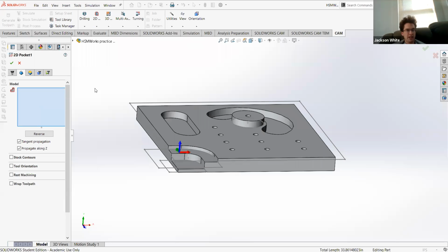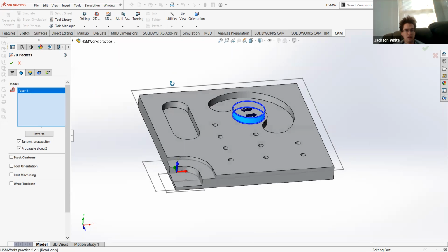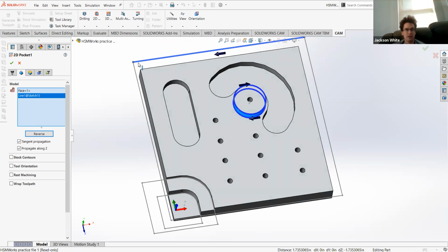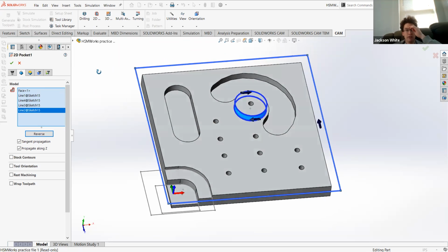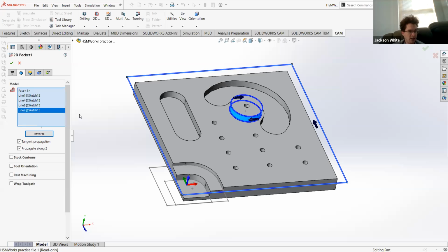And then you start actually getting to where we want to get. So for this, we want to get the outside here and then all the way to this. So in this case, it'll take all of the material that is in between this rectangle here and this boss extrude here that we were making sure to preserve.